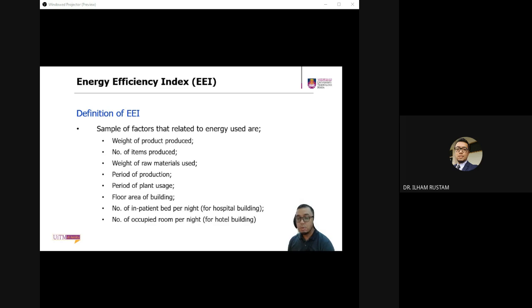Especially for this part, whether you like it or not, you have to refer to those who are fluent with the system, with the process, or the engineer, or somebody who designed the machine, because you need to be able to measure correctly. There's no point in you going through the trouble of measuring this parameter, only to find that the parameter has no effect on the energy that you supply.